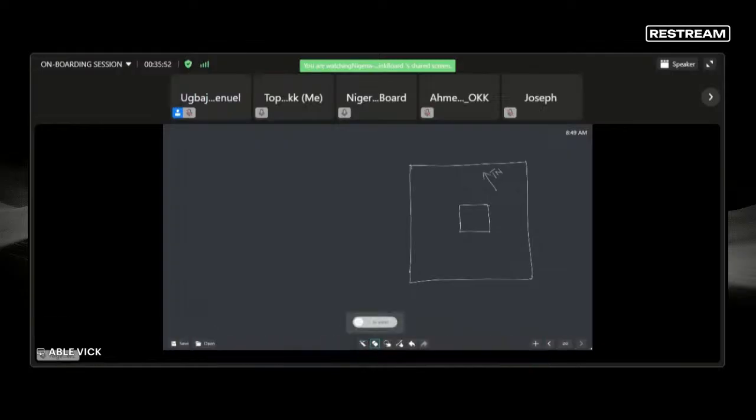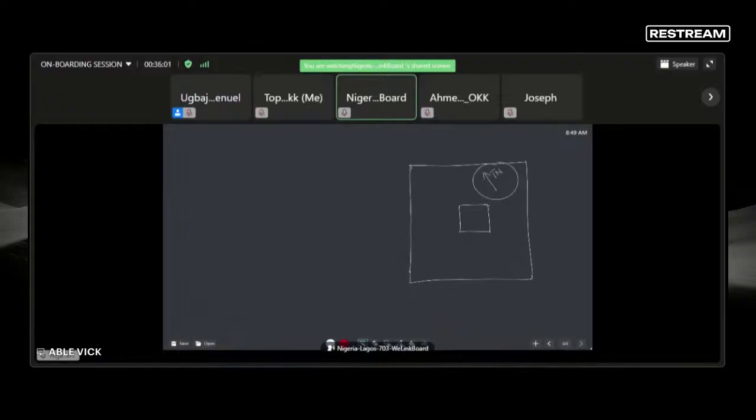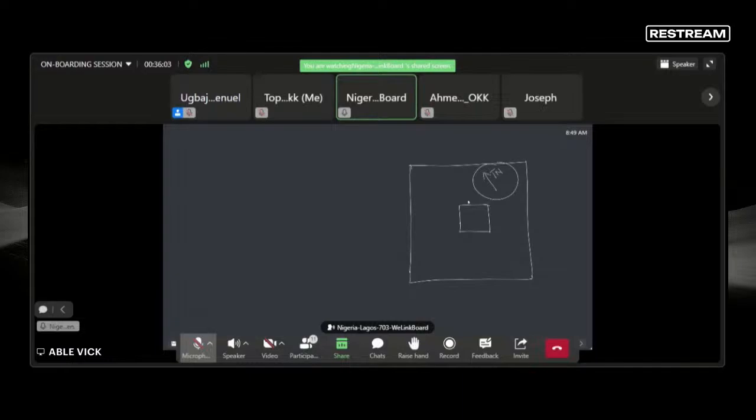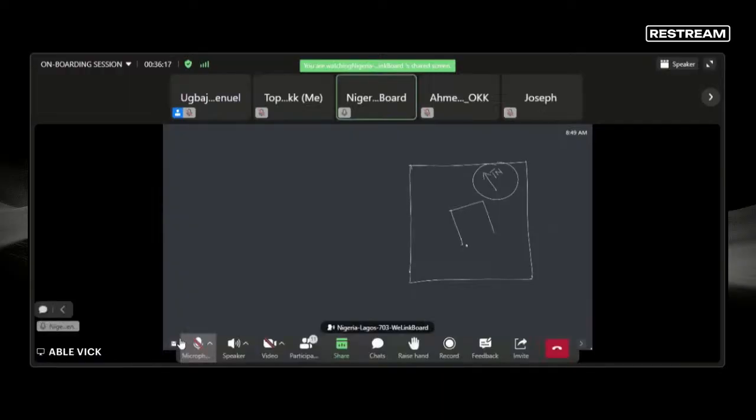True north. So you've gone the extra mile to confirm that this is your true north. You've confirmed that part. So why is the foundation? If this is true north, very okay. It means this tower foundation should also be like that. So we'll be having something like this. We should be having something like this for our tower foundation. So it means the middle of that foundation must be parallel to the true north also.